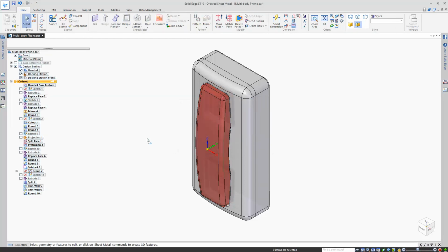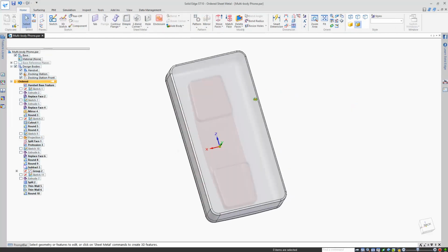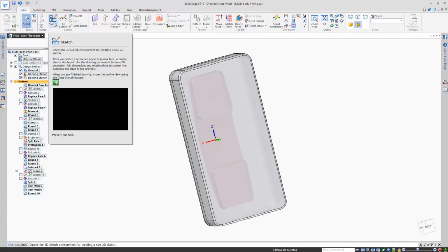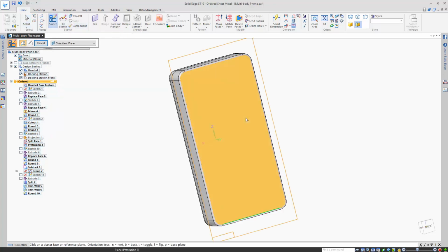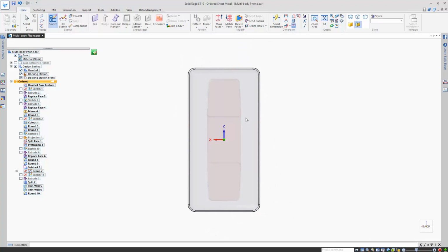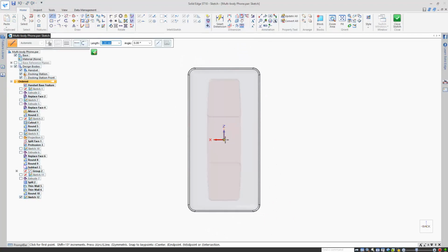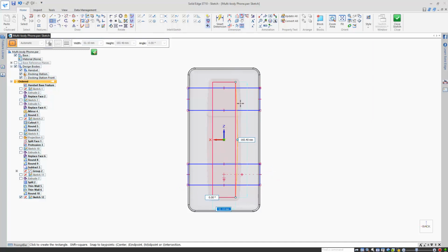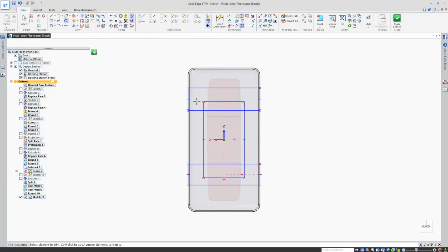For the first feature of this new sheet metal part, I'll sketch directly onto the back of the docking station, as I always want my bracket to fit around this part. The idea here is to use the existing geometry to drive key dimensions in the resulting sheet metal part. If you're familiar with IntelliSketch, this might be a good time to deactivate some automatically generated sketch relationships and add them manually. I'm making this with speed in mind, not precision, but in a more complicated multi-body part, changing IntelliSketch options may well save time.